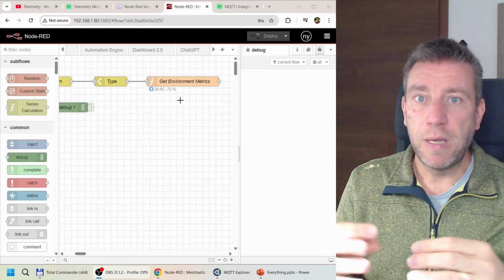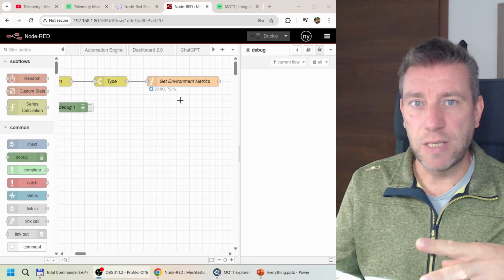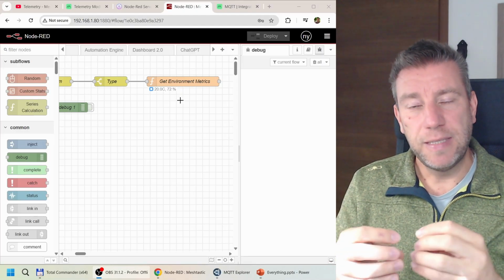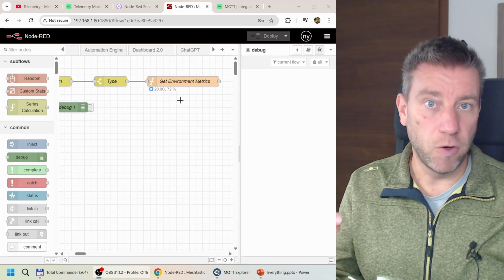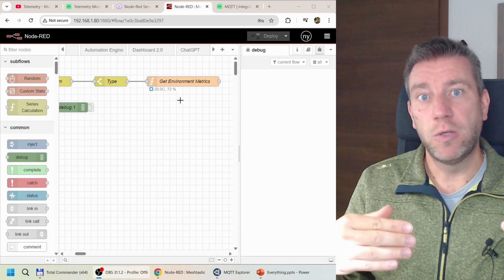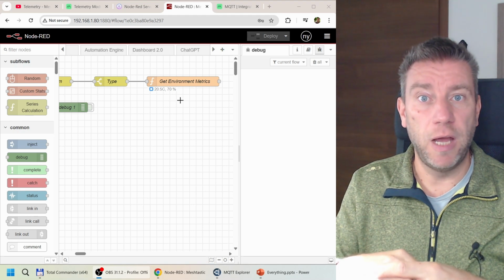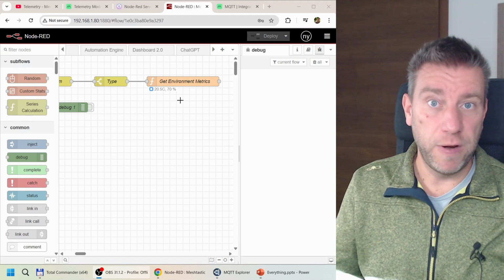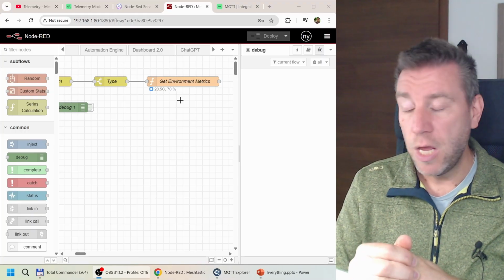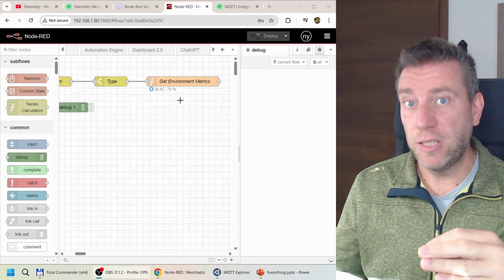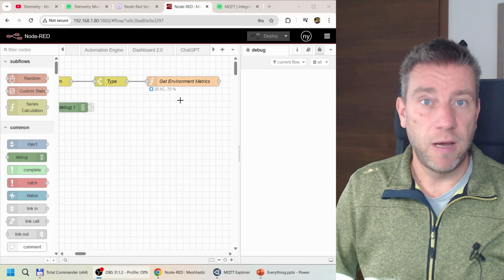Of course, you can do Zigbee, but they pretty much work on the same frequency, so the limitation is going to be somewhat similar. Maybe in some cases it's actually easier to extend the Zigbee range with another router, but that can also only go a certain distance. On the other hand, LoRa works at a different, lower frequency. It is designed for longer distance and low bandwidth communication, which means that potentially it would be easier to cover a distance with LoRa than with Wi-Fi and Zigbee.